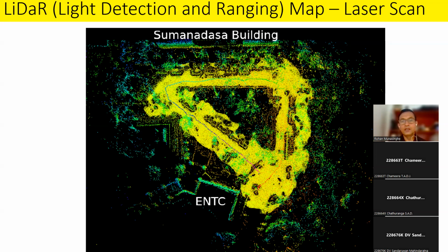And here you can see as the robot moves, maybe probably near the ENTC building, somewhere over here, it goes in this triangular road, and while it is moving, and then it is coming back to the same point over here, it combines all of these things. It has RTK GPS, it knows the position, and then the laser reflections around it, so that you can actually mark on the map the green areas. So this is traversability. We call it a traversability map. If you see these green areas, that is traversable, and black areas not traversable.